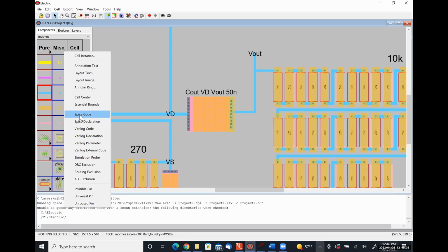They'd be huge. It is what it is, but your capacitor would take up effectively your whole damn screen for every capacitor that you were designing. So we chose to force the capacitor to behave that way with a heightened poly 1 to poly 2 capacitance by doing it this way. So you're linking it to the circuit by labeling the VD out. So those are the two nodes.